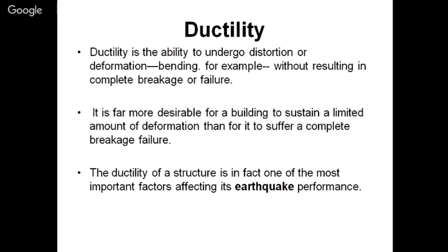That means if you are designing your building for more displacement, you are using your building to the maximum ductile performance. You are allowing more displacement with less forces and less damage. That is the use of ductile materials as per Indian Standard 13920, just for the ductile behavior of reinforced concrete structures.